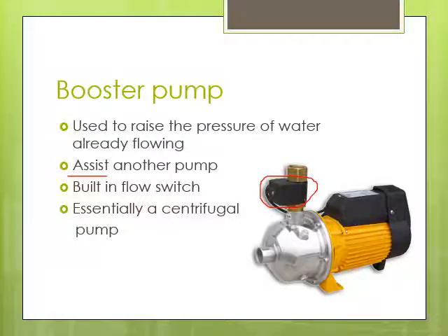So if you see the pump with something like this, it's either a booster or it could be a temperature override switch. Those temperature switches are common because if you run dry, say you run out of water, or worse yet, the pump doesn't shut off, but the water's not flowing, the water will get hot inside here and start to boil, and then that temperature will shut off the motor so you don't damage your pump. But oftentimes it's a flow switch.